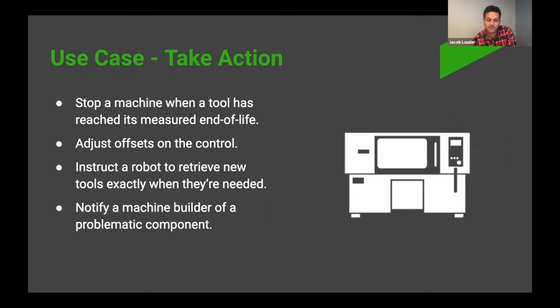Another approach to that would be to use sensors. For certain old pieces of equipment, it sometimes just isn't cost effective to get the right information directly from the control, and it's much easier to wrap a current transducer, for example, which measures the current as it's passing through the cable that's powering the spindle. And we can detect with our sensors at 500 hertz when there's a sufficient amount of activity on that cable to say that the machine's running or not. We also use a couple other techniques with some other components within the machine that you can sort of speak Morse code to us and tell us that a part was made. So there's a few tricks and tips that we have for getting machines to provide really accurate data through sensors as an alternative approach to going directly to the control.